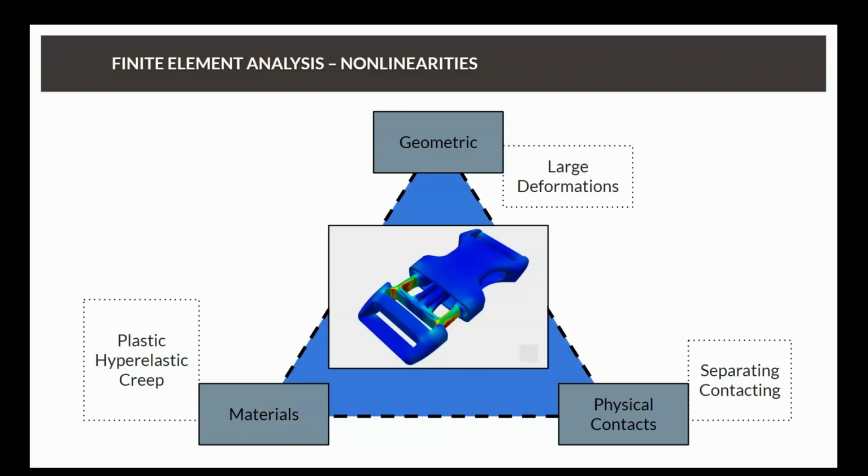And the same goes for a large deformation in a simulation. This large deformation is essentially changing the structure, so the stiffness within that structure is going to change. The reference frames actually change for the structure, which means that the stiffness matrix will change, and therefore we're going to have to run it non-linearly.